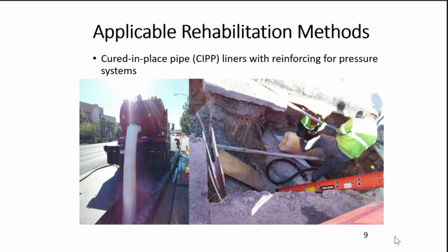So we drink water out of water mains. So they use different resins to make that hard liner that Ian showed. They use resins that are safe to interact with drinking water. The ones that are used in sewers are not safe, which doesn't matter, right? Because we don't deal with sewer water once it's disposed of, but drinking water is very important, right? So anytime, and that's the same for bursting or lining, any type of lining, whatever coating or liner you use that's going to interact with that water must be safe for human consumption.